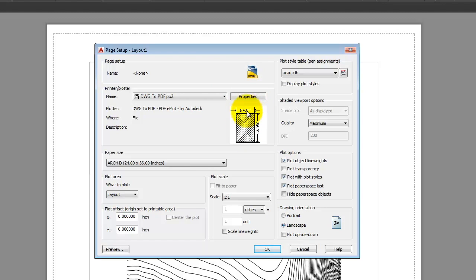Notice that the page here is 24 by 36 long. Right? Down here, we're plotting in landscape ultimately, so it'll rotate. It depends on the plotter. Generally speaking, the one on this row only has 24 wide. So when you print 24 by 36, it'll print the long direction. The one on the left over there has 36 wide, so it'll print 24 by 36 in the landscape orientation. The plotter is going to determine that. But if we pick the 24 by 36 sheet in landscape mode, the plotters will adjust for us.